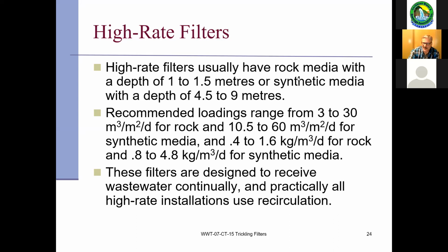If we want to take a guess at it, it's not a highly technical question. Basically, the space between the media with rock is a lot less than with the synthetic media, like we talked about. So keep that one in mind. With the rock media, you have to have less of that media in place, whereas with synthetic media, because you have a larger area for the media growth, you have more area for the airflow to pass through, so you can have a much higher depth of media.